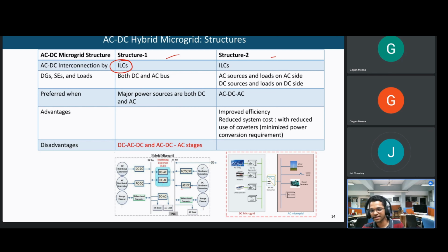But if we have a mixture of AC and DC, then it may be difficult to geographically separate them, right? In case of renewables, mostly both AC and DC generations are coming in a particular area, like some windmills, some solar, some battery storage. It may happen that, because we don't have wind everywhere, let us say in Tamil Nadu where wind is more, there is a prominence of wind in a certain locality. And that can act as an AC microgrid.